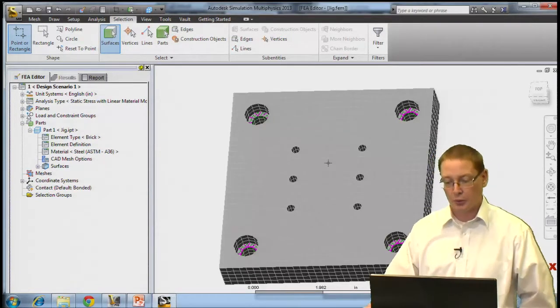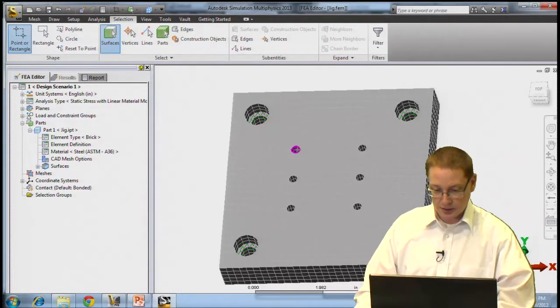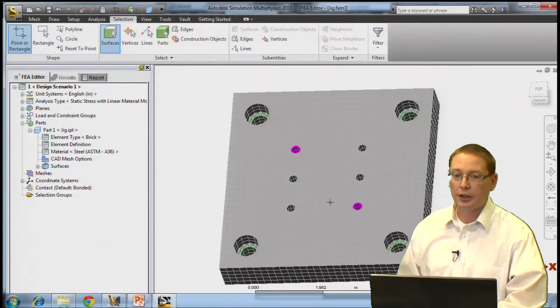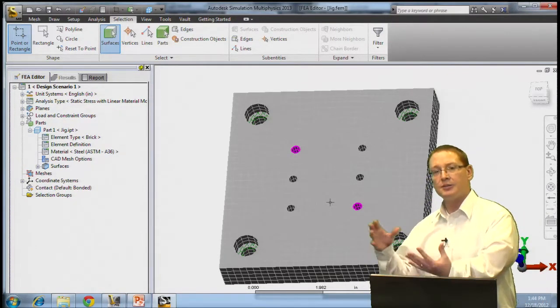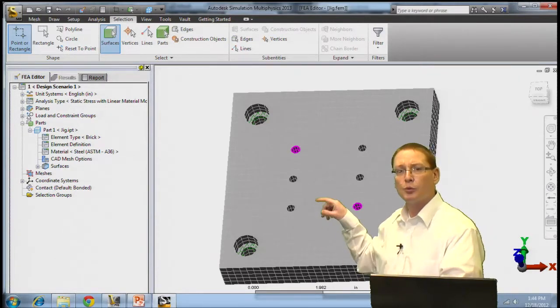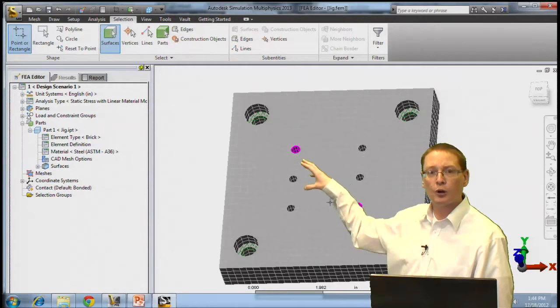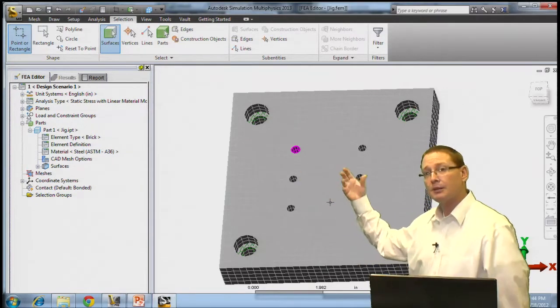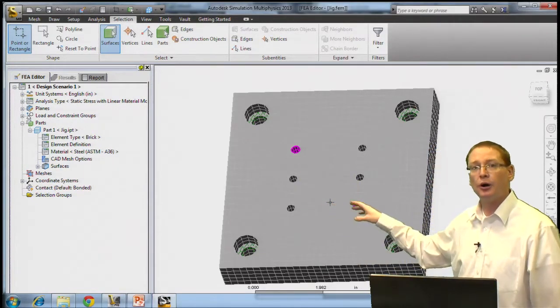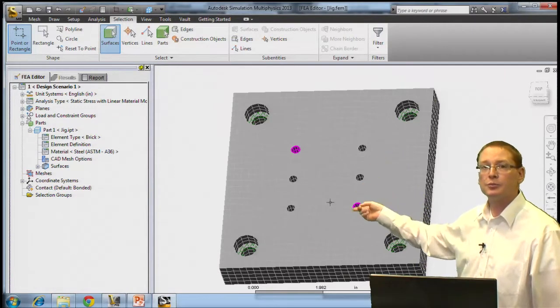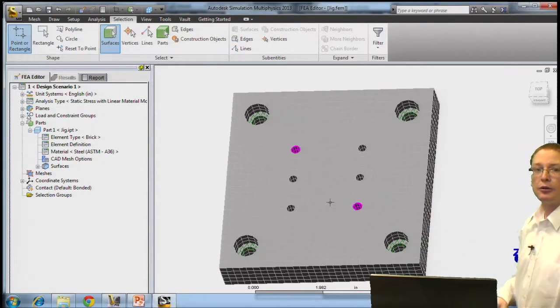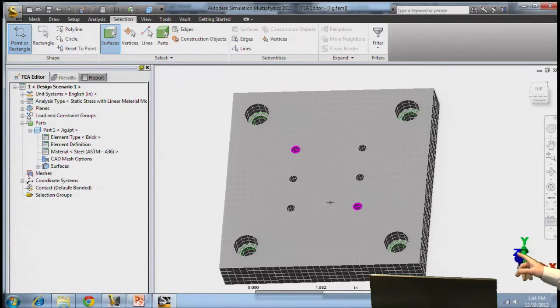So I'm going to select 2 of the holes here. I'm going to select this corner here, and I'm going to say that corner there. And whatever it is that we have attached to the structure, whether we pin something in or maybe we pin it in and weld it so we can hold our workpiece, whatever the real world scenario is, ultimately what we're getting is some sort of force out of the plane, or if I move to the side, in the Z direction.